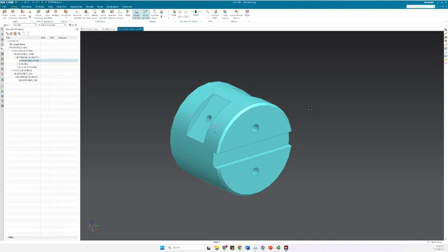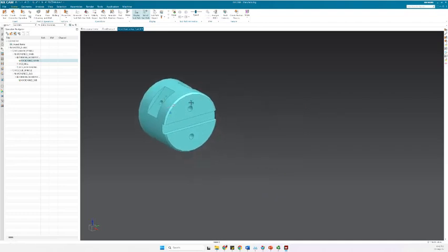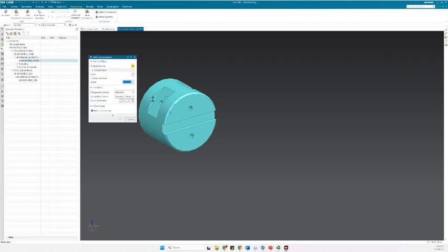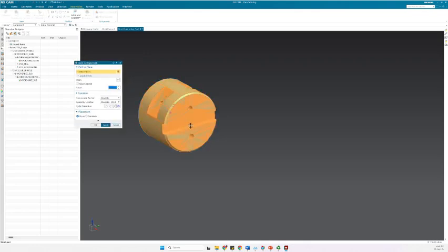So the first step was actually to create a copy of this part. So what I will do, I will go to the assembly tab. I have it up here. If you were not able to find it here, you should be able to find it in the application. I go to assembly, and now I want to basically add another component. Either I can reload or open another file by choosing a file select, or I can just click on an existing component